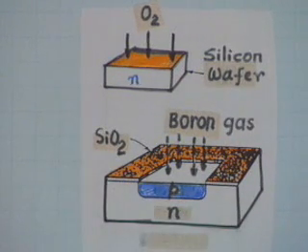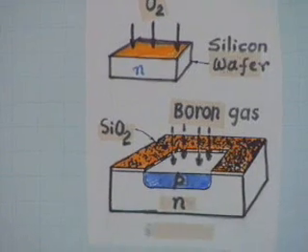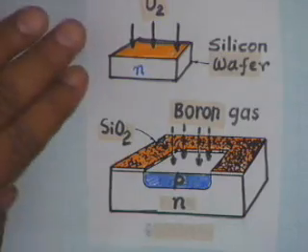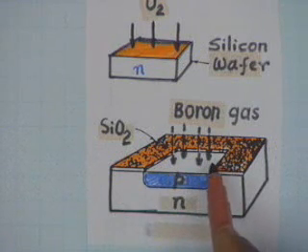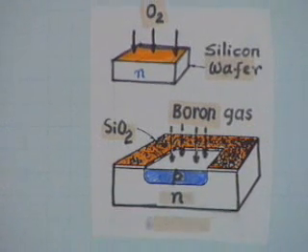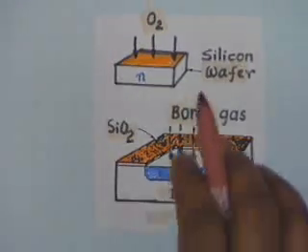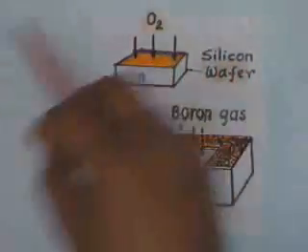Then what I do is, on a piece of mask, there are special types of masks that can be prepared. You make a window on a mask, all right, and you cover the silicon dioxide with this mask. Then pass some etching agent like chlorine. Chlorine in a gaseous form would do. That eats away a part of silicon dioxide. That is, whatever the mask opens, chlorine goes into it and eats away. This is called selective etching.